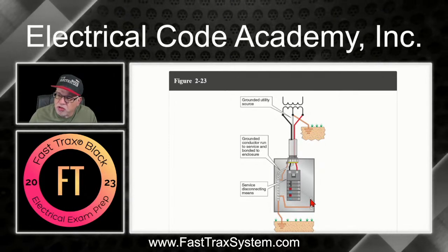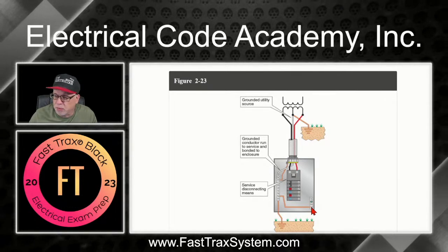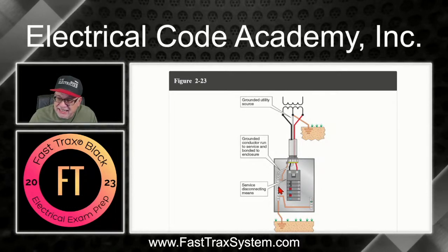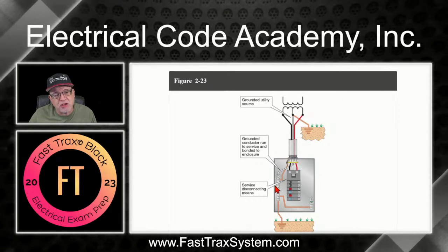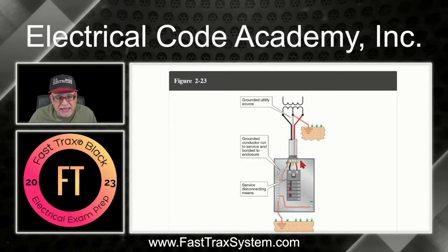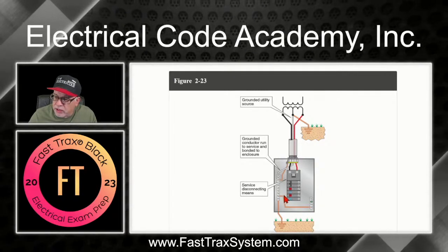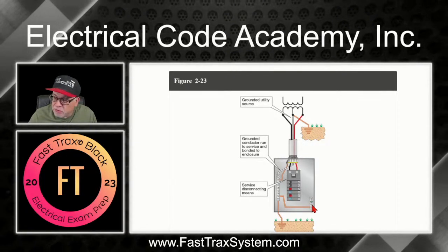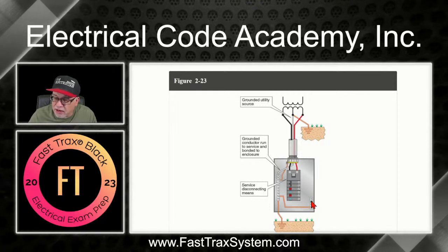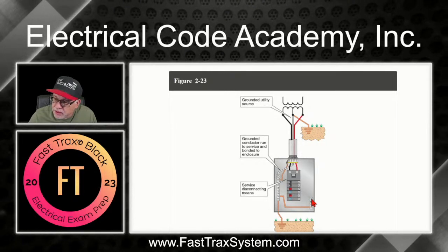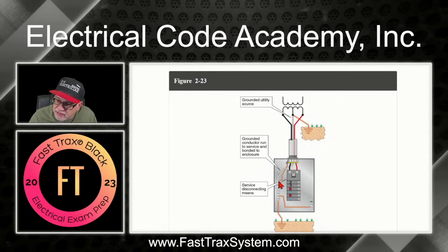And so this is your equipment grounding conductor terminal bus, but it has to be connected over to the grounded conductor bus, and it can't be through the metal enclosure. So this right here has got to be directly connected. Here is the main bonding jumper in this case. Now we could eliminate this, take this bus out, take this ground screw, this main bonding jumper, and connect it over here onto this bus, and now the green screw is the main bonding jumper.